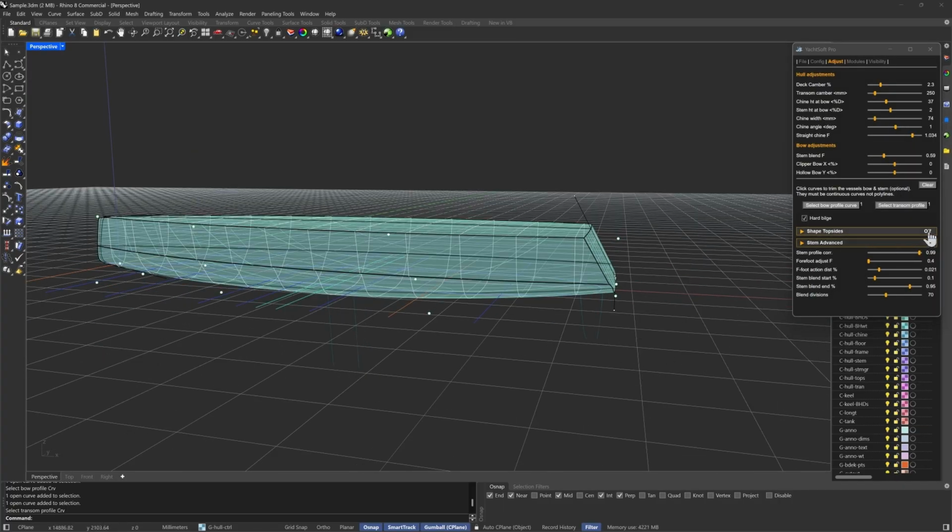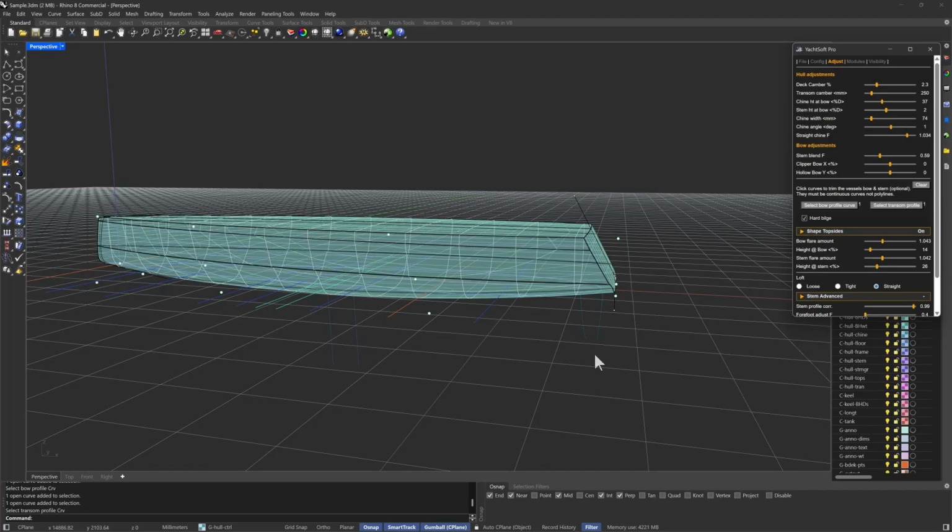You can also add shape to the top sides. This is sort of a percentage down in the bow, a percentage down in the stern, and a percentage increase in beam. So the lines will appear first. I've got lines switched on by default, which slows things down considerably. So there you've got a topside shape.